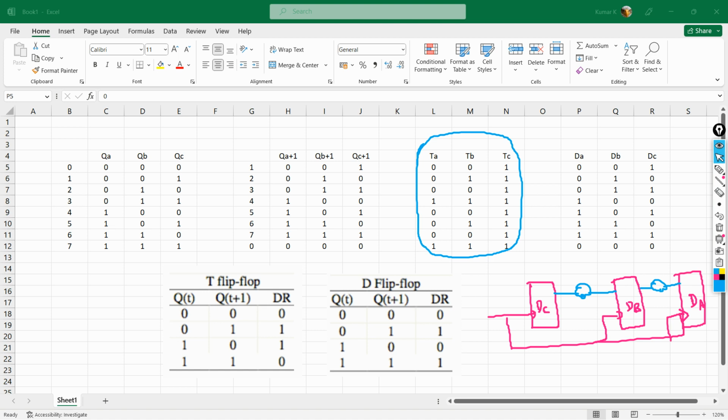Your goal is not to design this, but to have an idea of this circuit. Now, remember, the reason why I am talking about this is that it is something you will deal with every time, register to register. Ideally, I would say this particular path is something called a reg to reg path. So, when we do static timing analysis, you have to look at what the logic is, how much time it takes to travel, and all this matters.